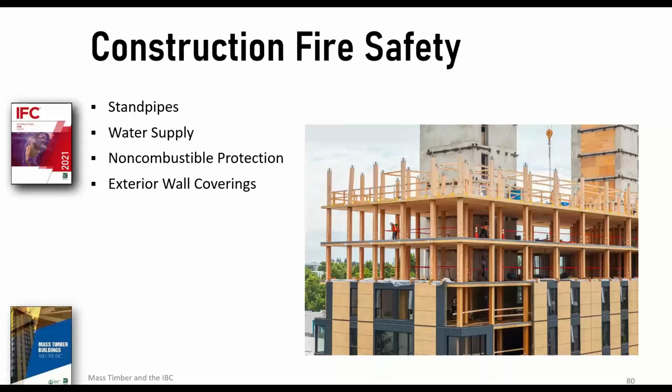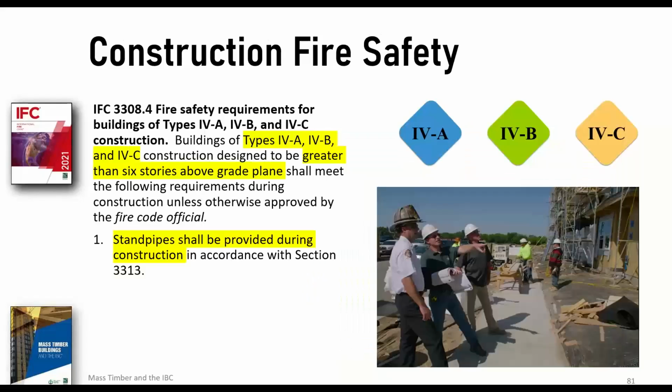It's panelized construction. The panels are fabricated off-site. They're brought on-site and usually assembled fairly quickly. So there's not a lot of combustible building materials laying around. There's no waste or very little waste. So that in and of itself helps the issue. But the TWB added some.